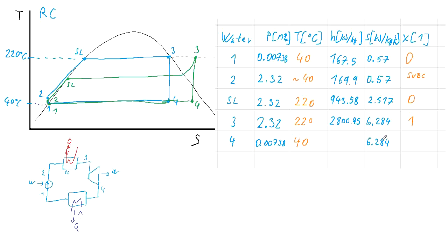If you are using those, you find the point of the pressure, or the isobar of this pressure, intersecting with this value of entropy, and the value of the enthalpy will be 1956.12 kilojoules per kilogram.